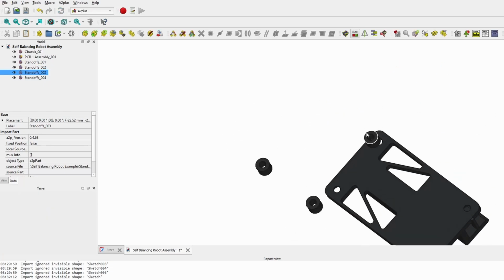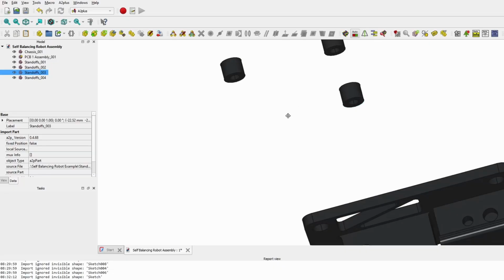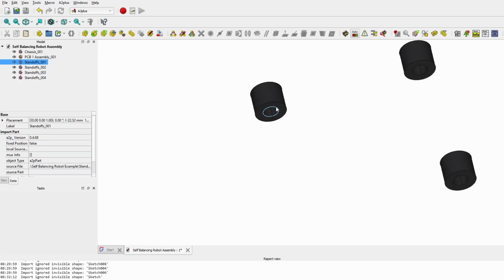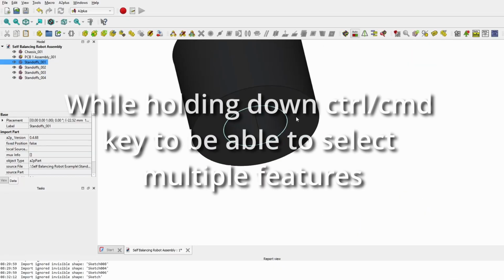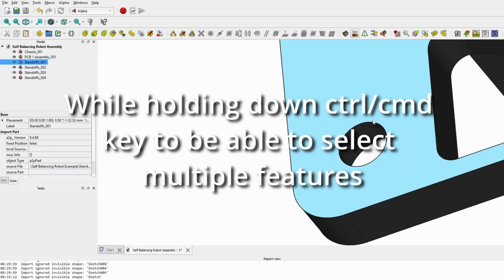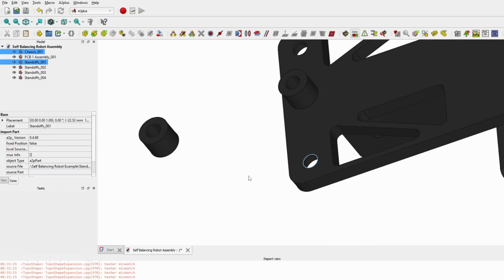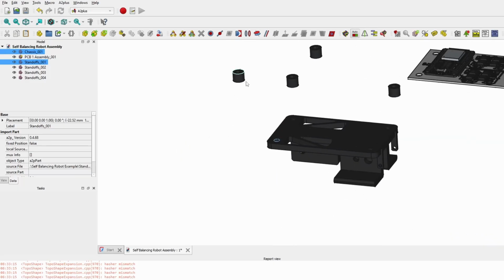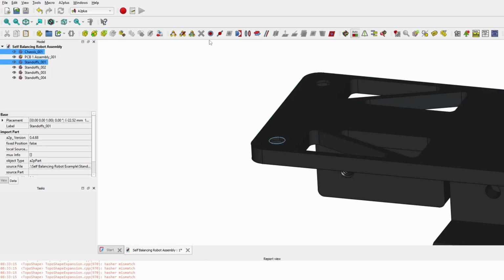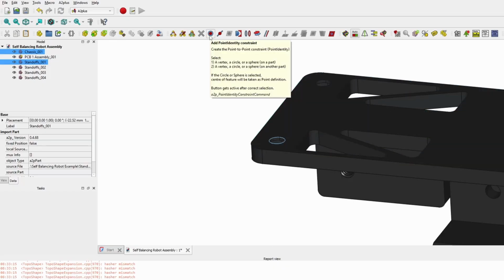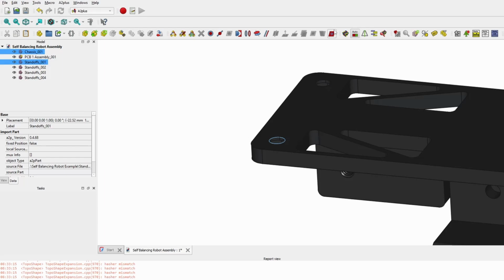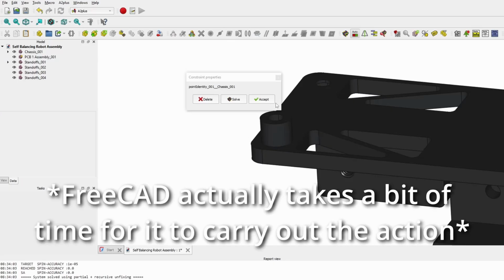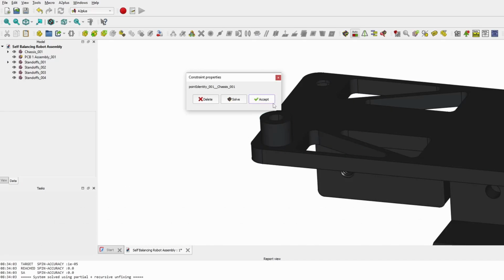And now we actually want these things to be aligned to these holes so that we can properly see how it all works together. So how we do that is we essentially select an edge that would fit in or fit around this edge right here. And essentially what we say to the CAD software is we want them to merge together, to kind of move to match up and couple with each other. You can use that with this tool or that tool. Multiple tools generally work. I'm just going to use this one. Okay, there we go. It popped into place. So just accept that, obviously.